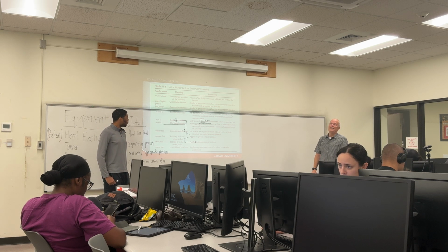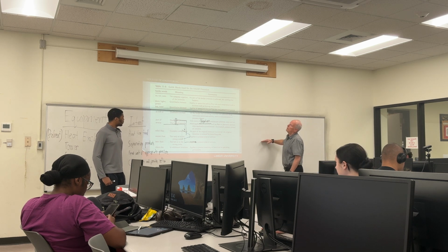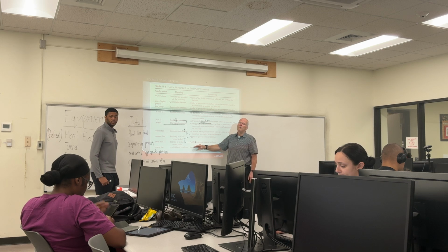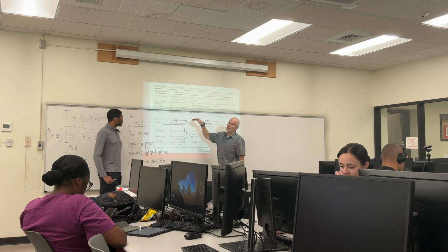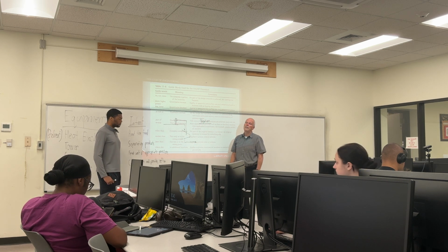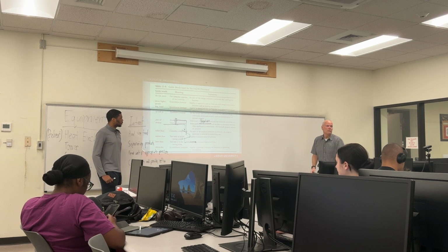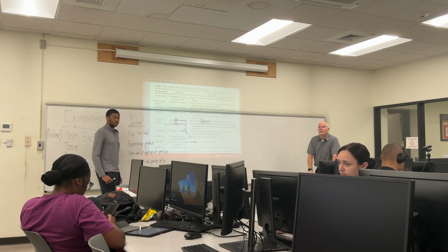If you didn't do anything else, what's to stop the flow from going backwards, back through the compressor, back into the pipe? What's to stop that from happening? You didn't have any controls. You didn't have any safeguards. The check valve is a safeguard. Nothing was stopping it.